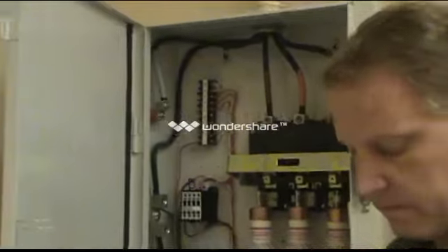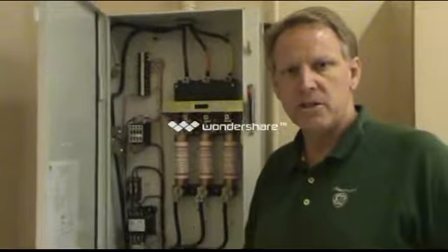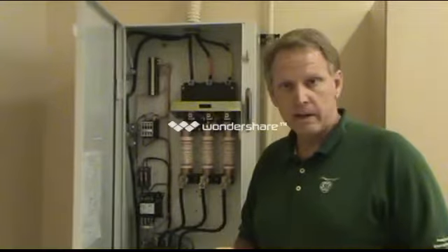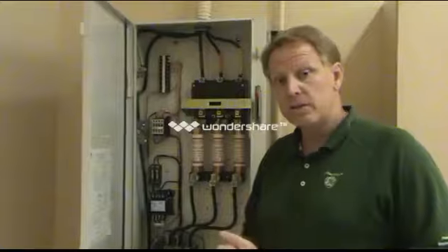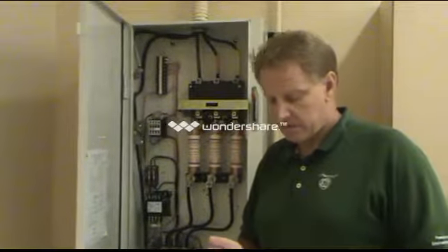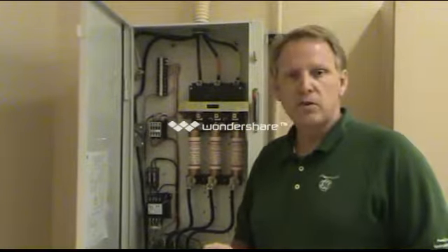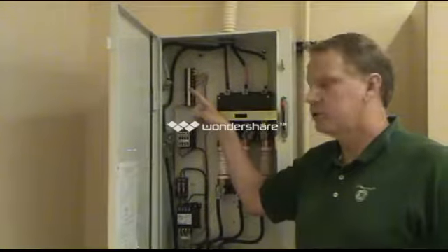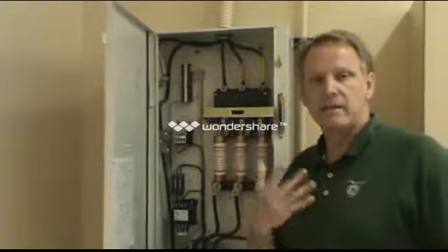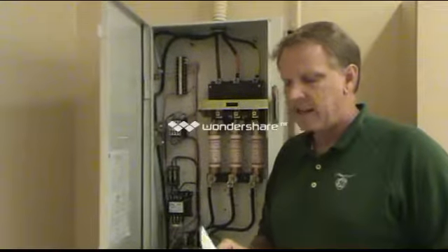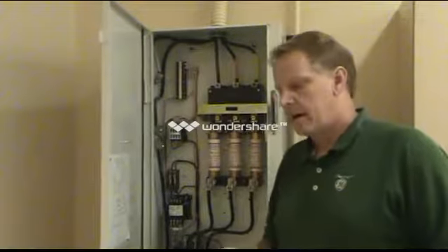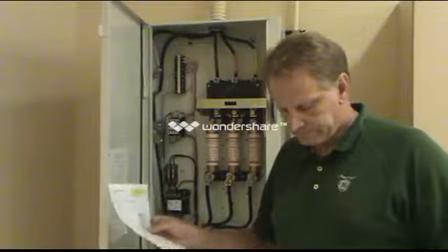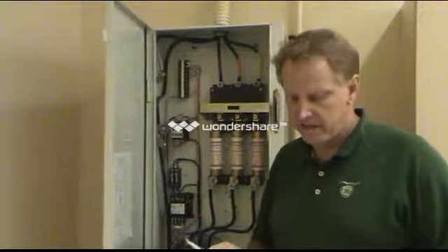The reason is we can get some valuable information on the style of transformer, correct wiring, etc. Even though we're not using it, it's going to be good information for us to know. And the last voltage measurement is going to be between your ground and your neutral. All right, again, that gives us valuable information. Tells us the health of the system, the type of transformer we're looking at, etc. All right, we're going to run on to the next page.